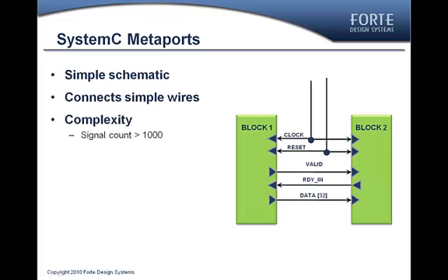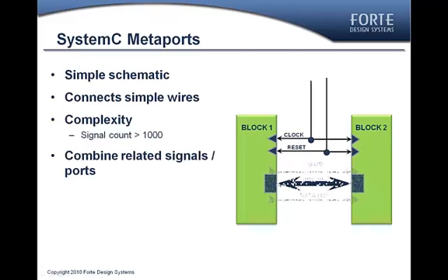However, it's not uncommon to have many such signals, sometimes in the thousands, and the complexity of dealing with them gets out of hand. It's also evident that in many cases there are a number of signals that are related to each other. For example, they're the relevant signals in a particular ready-valid handshake. So to hide a lot of that complexity, multiple related signals can be encapsulated into a single metaport, and each block now only has to deal with connecting up a single signal to a single port.